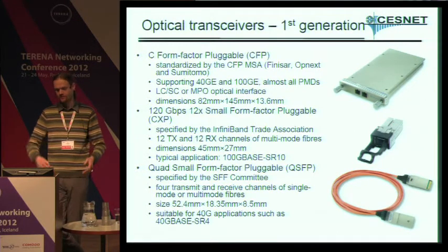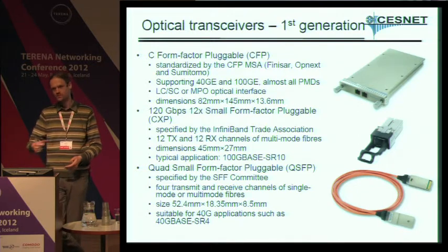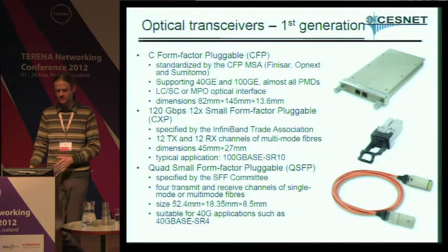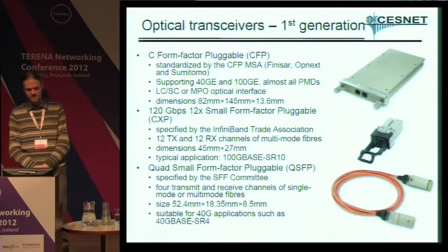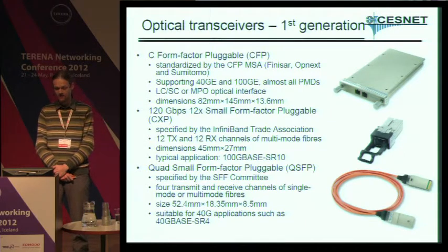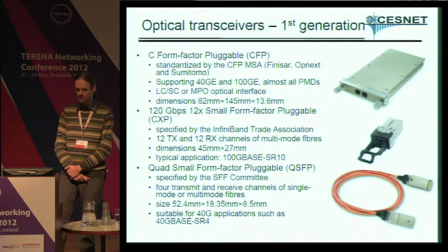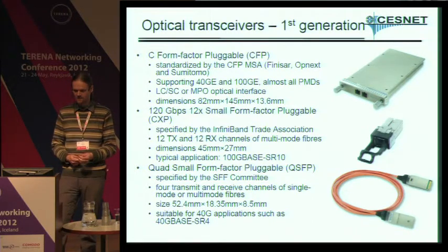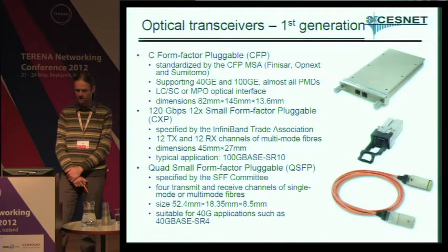Almost every flavor of the Ethernet, long range, short range, 40 gig, 100 gig, multi-mode, single mode, almost everything is supported by CFP. However, CFPs are huge. We're building a PCI Express card, and we would be able to fit maybe one, definitely not 2 of them into the slot. So CFP is universal but big.